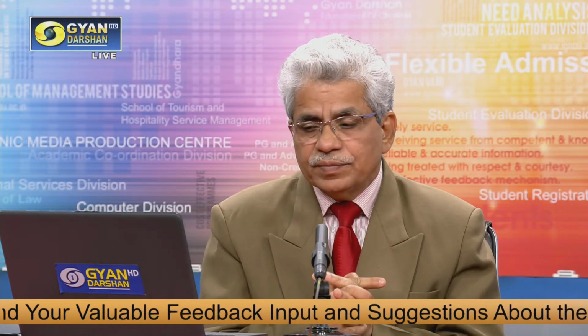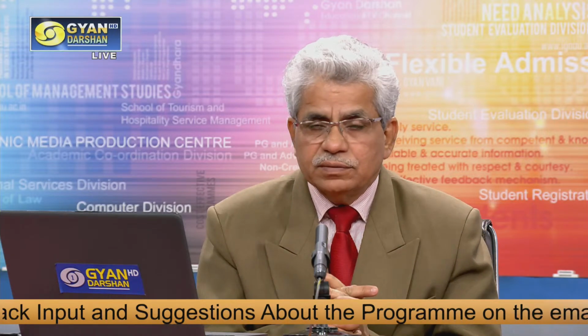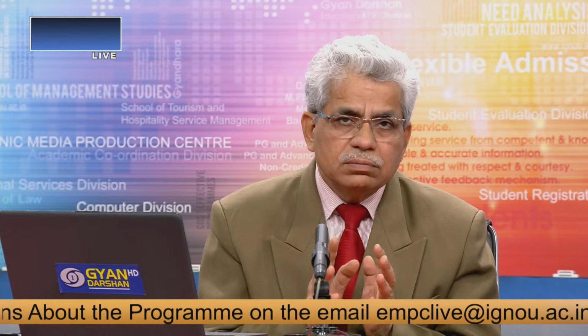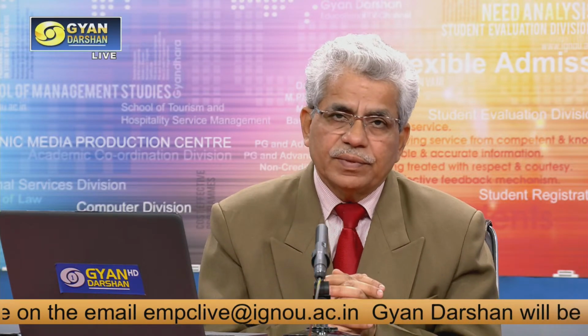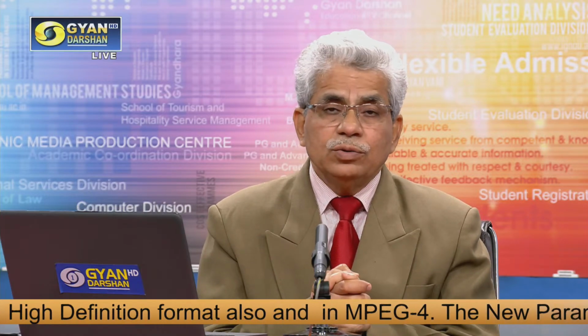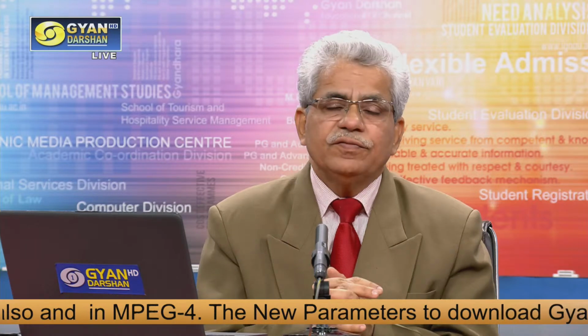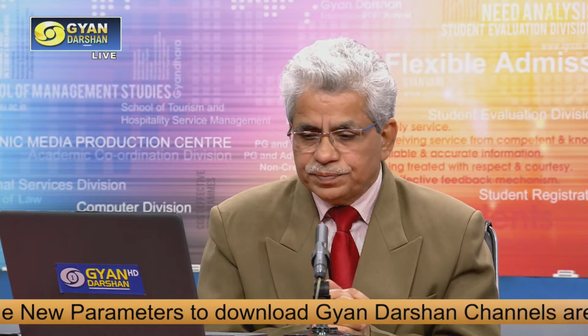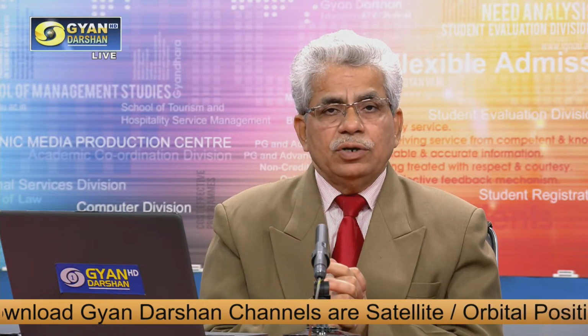Then the third thing is that you should avoid any awkward position and hand position. You should not operate with wrong positions. Your position, how you are standing or sitting while using these power tools, how you are handling them, how you are putting pressure on them. All these things are very important. Then again, your secured footing also: you should stand with firm footing. You should not stand in a casual position. So take a secured footing position when you are using power tools. That should be told to the workers.